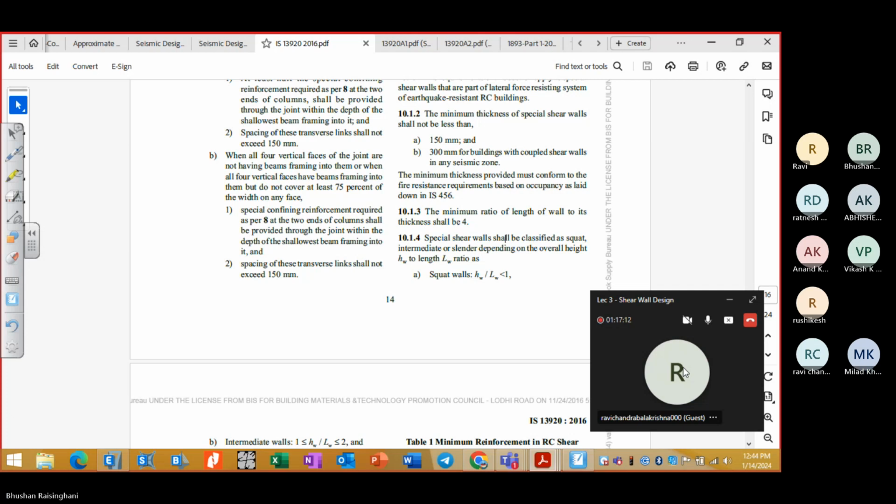Yes, concerning the question, usually when we use it as a column, the system during analysis will consider that there is some redundancy in the column, which means the end support of the column will become like a hinge. Those hinges cannot support a moment. Furthermore, when I consider this element as a frame member, now this frame member can support moment, so it becomes more resistant.